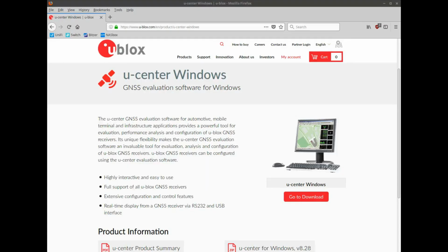On the u-blox website, you can download the documentation for the message definition as well as a free tool called uCenter, which allows you to communicate with the u-blox GPS. As you see, uCenter is only available as a Windows application and needs at least Vista or better. I use Linux on my PC, and fortunately uCenter works fine if you use Wine emulating Windows 10. There are also Windows device drivers available for download on the u-blox website, but as uCenter in Linux works without those drivers, I can't tell you anything about them.